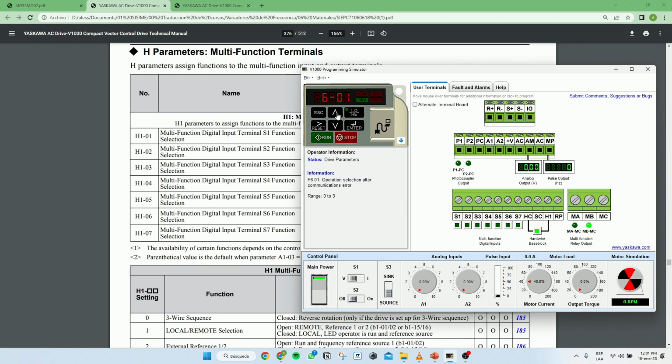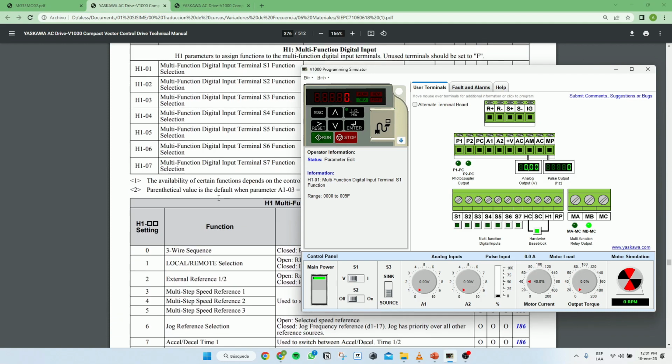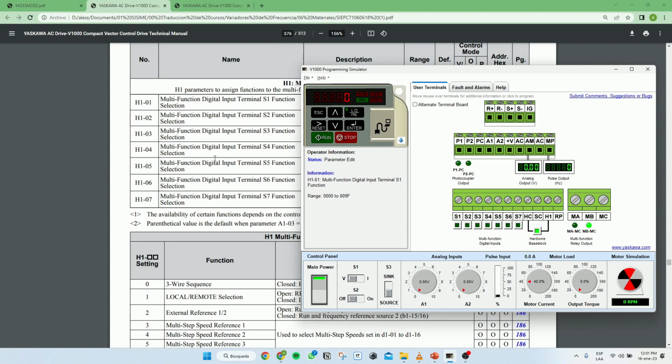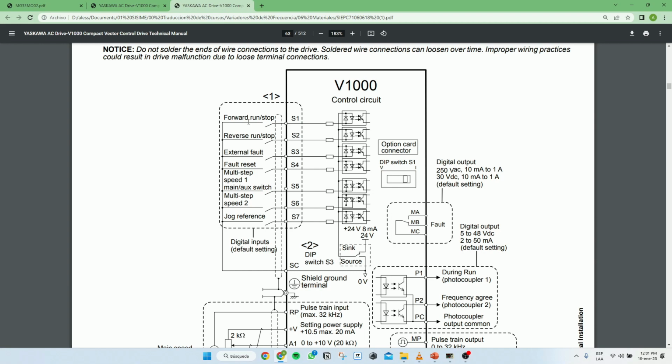And we're going to follow H101, which means that this is going to be our digital input. Okay? And so this is going to be number 40 by default, as we can see here. But I want you to please help me out by assigning these inputs their functions according to what we have as an example, for example, page number 54 in your manual.